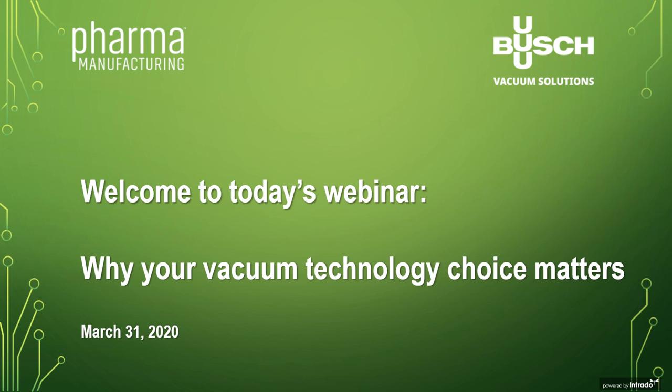Today we're going to talk about how to choose the right vacuum technology. It may sound simple, but there's no single ideal solution for all pharmaceutical applications. So when going through this process, all of the parameters need to be carefully considered in order to derive an optimal solution. Vacuum technologies have also been continuously evolving for the past 2 decades, so it might be a good time to reevaluate your options. For example, replacing traditional liquid ring vacuum pumps with dry screw technologies can reduce energy, increase reliability and performance, and benefit the environment, as well as save you money.